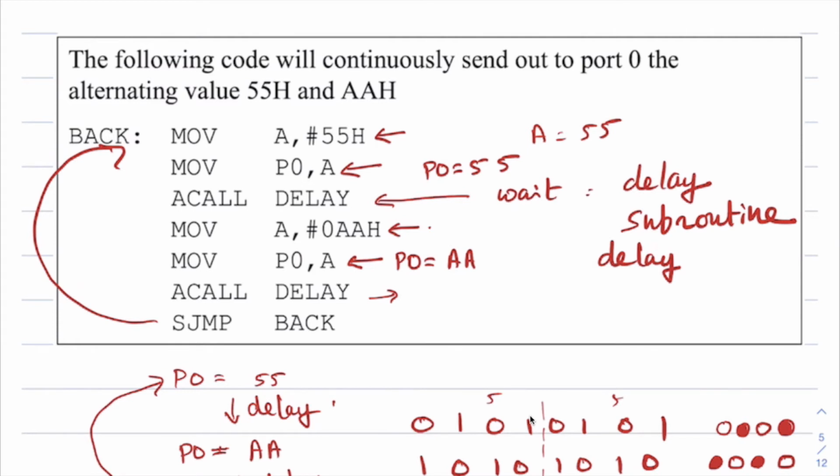So now if we need to configure this port as an input port, then definitely we need to write one to each pin, or FF to the entire port. So this is one of the important things you must realize. This is a speciality of port 0 only. That is, the default value is output when it is pulled up already.